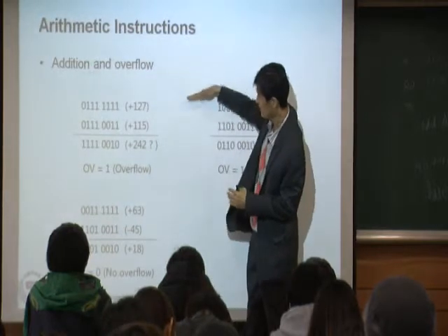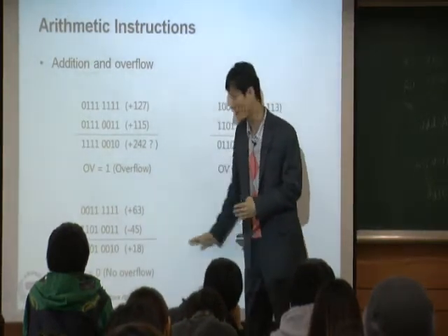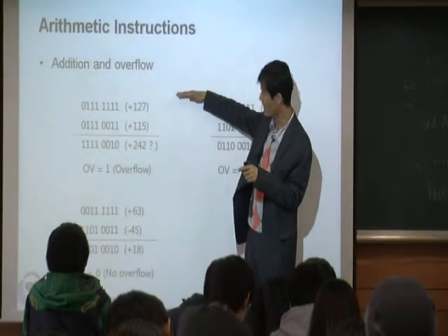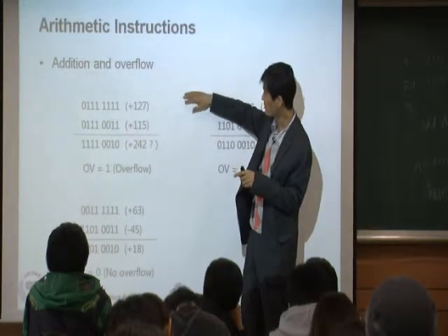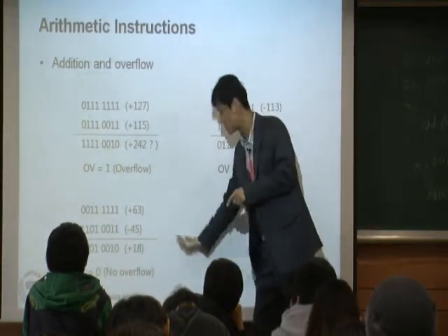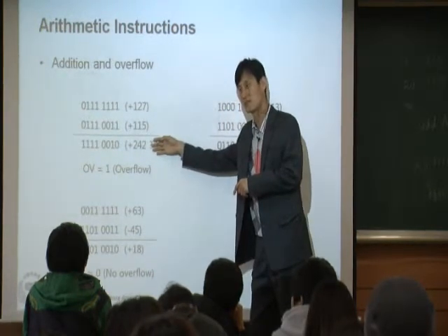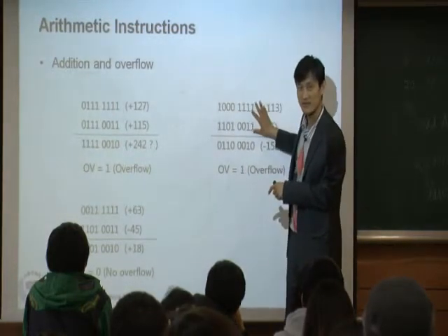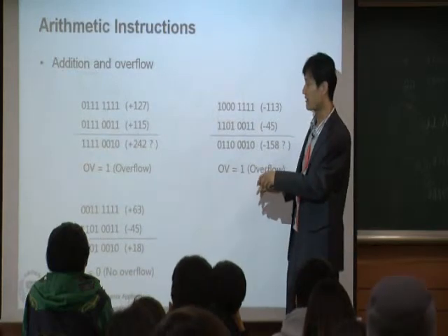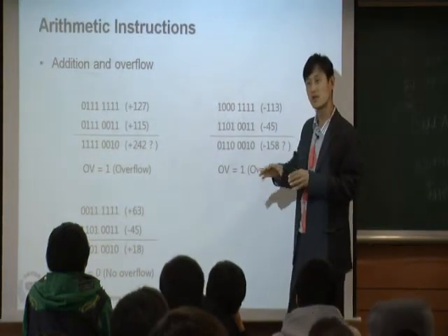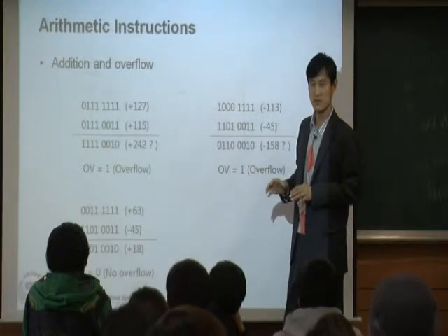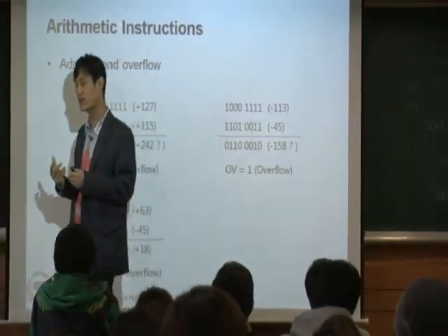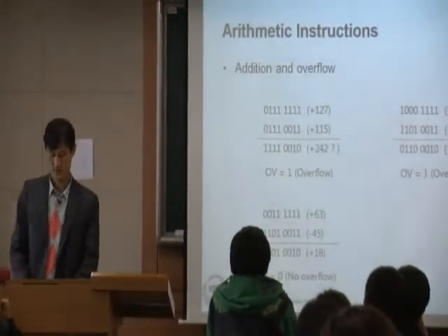In this case and in this case, what happened is you have a positive value. Let's say here is 128, the top 127, and the bottom is minus 128. You have some positive value plus another positive value. When you add these two, the result becomes too big, so you wrap and it becomes negative. That's this condition. Second is that negative plus negative goes back and becomes positive. So those are the conditions where you have overflow. And this overflow is giving you a warning. Okay? Warning. Please be careful. This condition may happen. And when you read this one as signed, then you have to worry about the overflow condition.